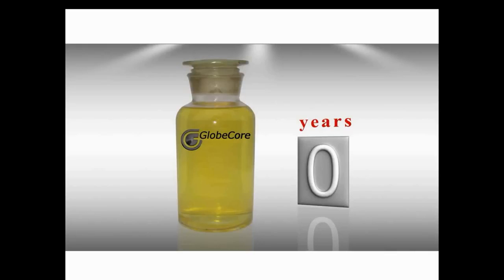Now, let's have some more definitions of oil conditions. New oil is obviously deemed to be unused. Re-refined oil is an old transformer oil passing through a refinery process. As a result, we get basic uninhibited oil. This process is currently unpopular. Some companies talk about refurbished oil, what we call an output of degassing or purification.